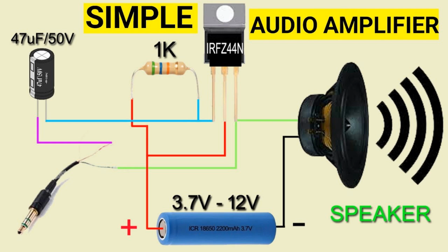Heater control. In applications requiring precise temperature control, MOSFETs drive resistive heaters. By adjusting the duty cycle of the MOSFETs, the power delivered to the heaters can be controlled accurately.